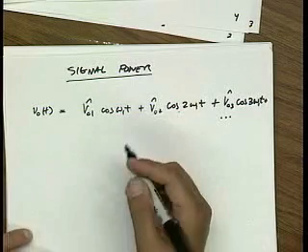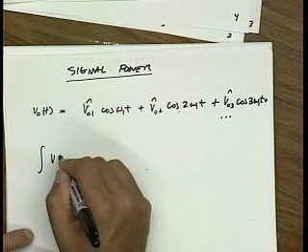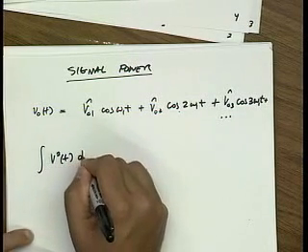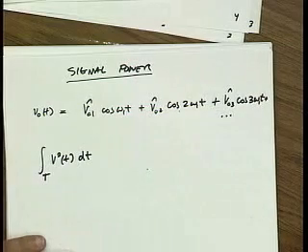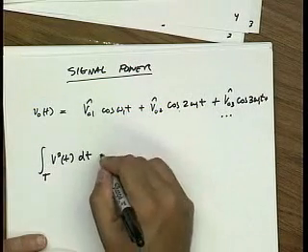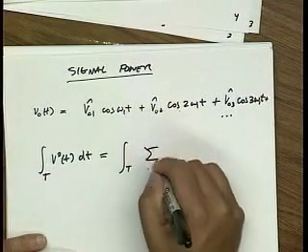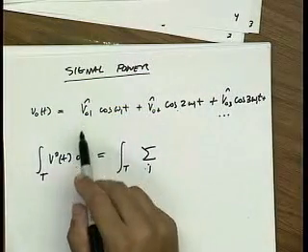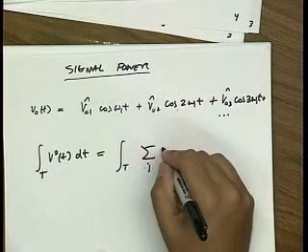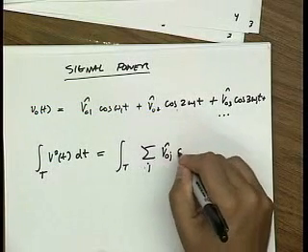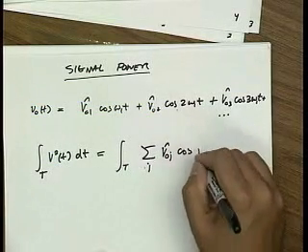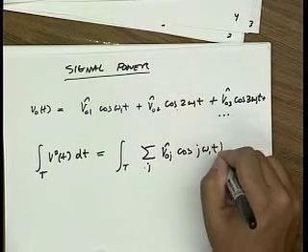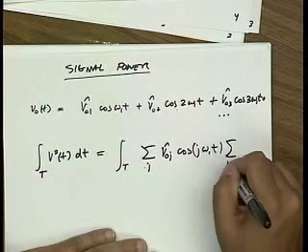Okay. Now, by Parseval's theorem, we know that for a periodic signal, if we want to calculate its power, let's say over one cycle, we basically can take the sum of the magnitude squared. Actually, I did this a little more messy than I'm just going to derive real quick Parseval's theorem.